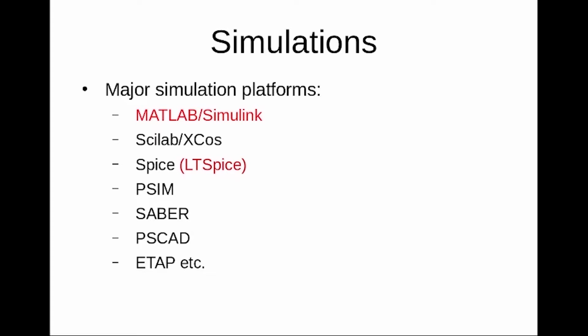We choose MATLAB Simulink mainly for system simulation and control design simulations, and in order to do it effectively and quickly, most of the time we will adopt idealized models, but you can always include non-idealities in your model. The only thing is that it will make it more complex, somewhat more time will be taken for simulation, and sometimes you need more computational power also.